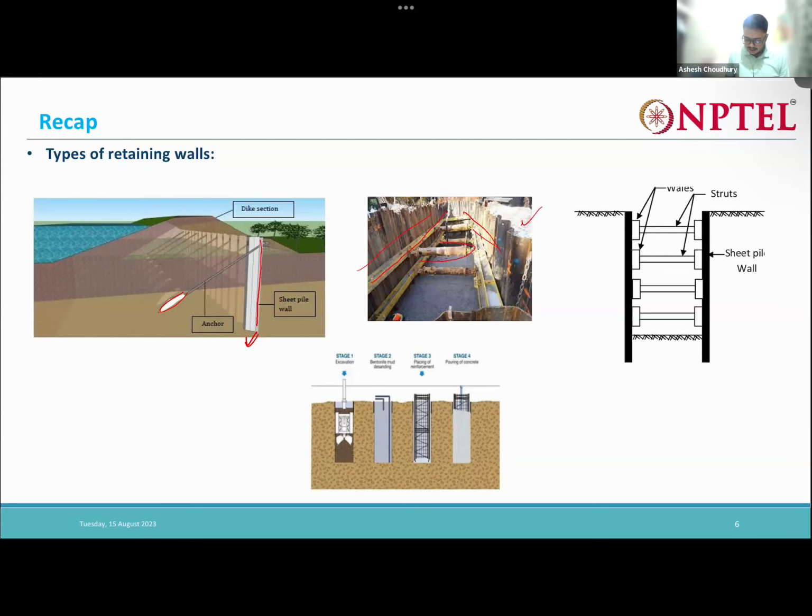You can see here a wall 3.6 meters high, with 0.3 meter wide modular blocks placed, and with their help our reinforced soil is constructed. This part is the reinforced soil, and this part is the other retained soil. All of this soil is called the backfill.